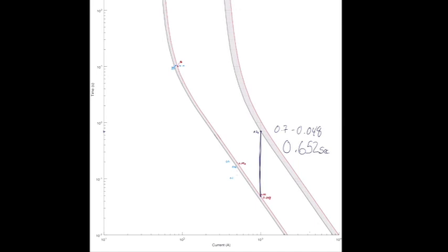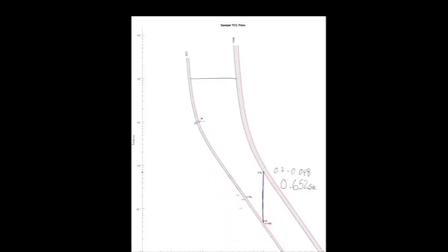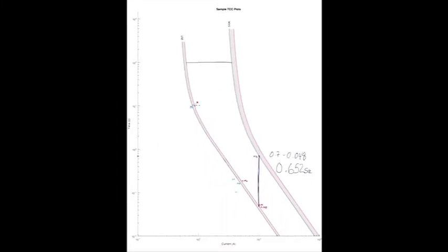We could also ask a question at 100 seconds. How many amps difference is there between the 25T and the 140K? And again, we're going to want to compare our closest lines. So we're going to want to solve this line right here. So for our 25T, we're in the block between 10 and 100.